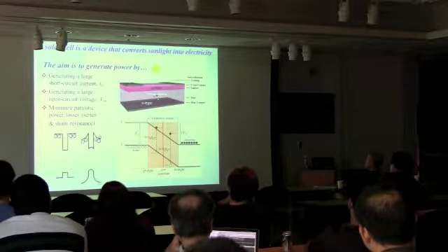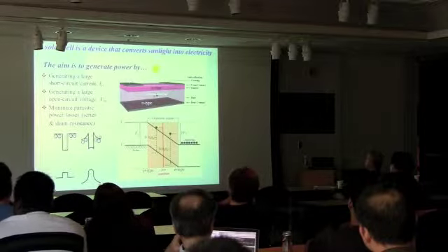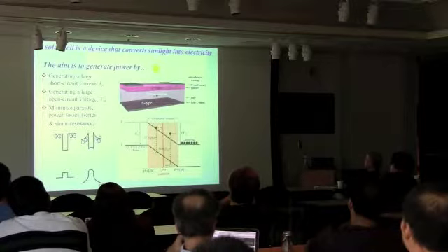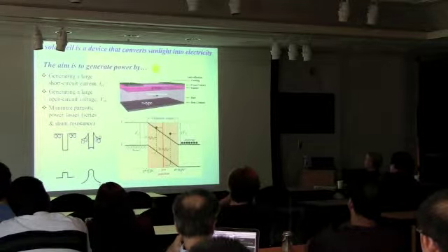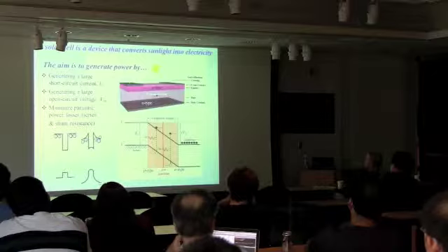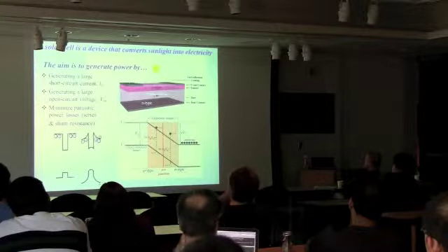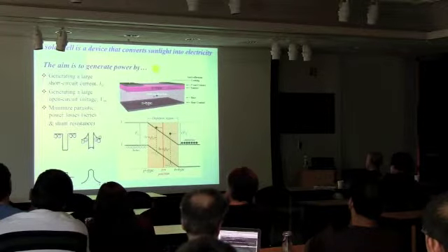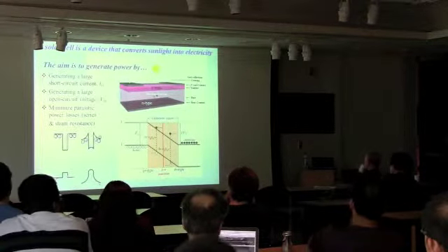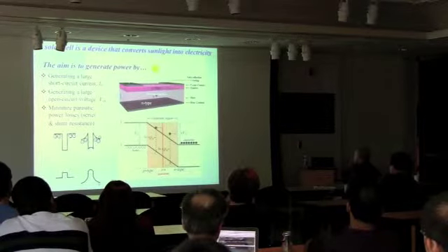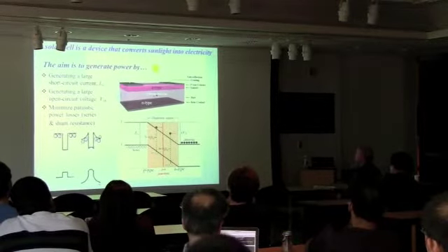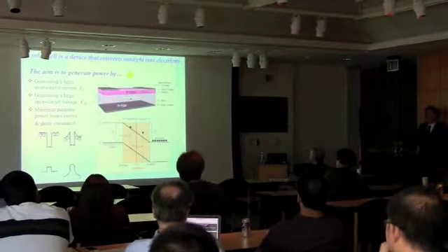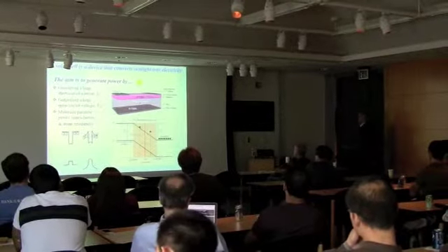The light is absorbed in this depletion region, and the field will drag the electron that is created to the N contact, and the field will drag holes to the P contact. So electron-hole pairs are separated, and as they separate, they cause current in the external circuit. So you have the contact, you have this load, and you have current between the P and N regions.